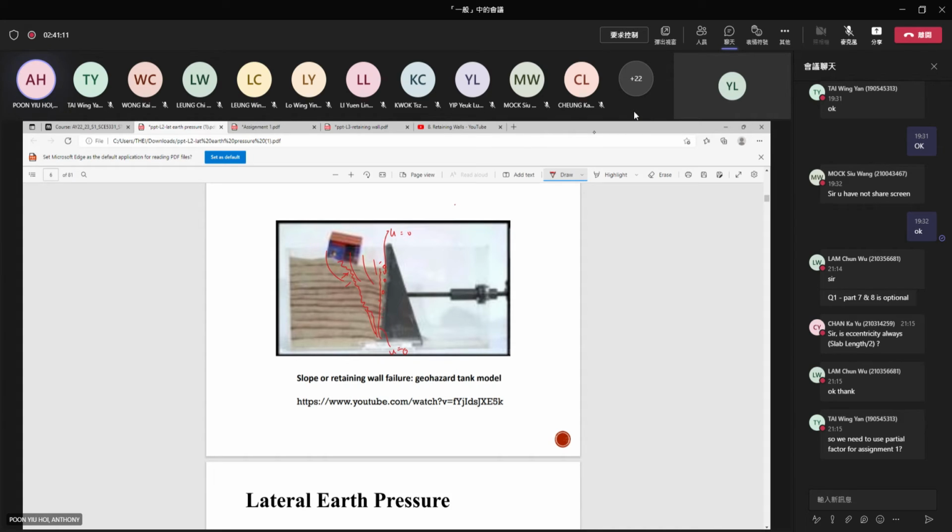Along here, because you put a drainage layer there, the pore water pressure is 0. This is good. But what about along this line? We still have water pressure actually acting through it. So even if we have vertical drainage, we still experience some sort of pore water pressure along the slip surface.